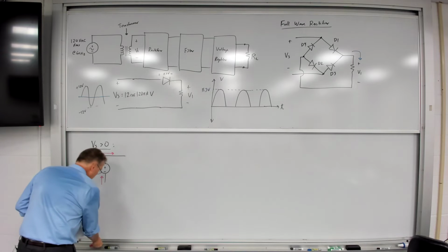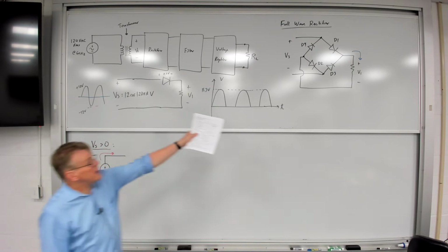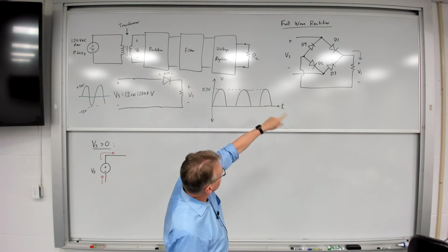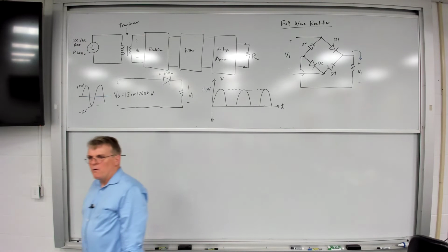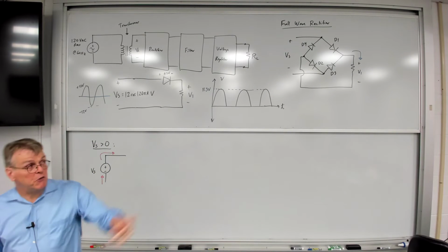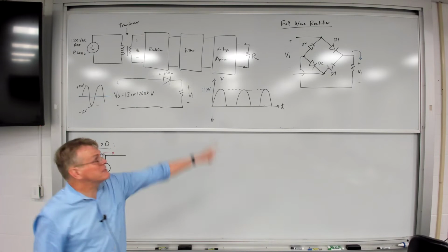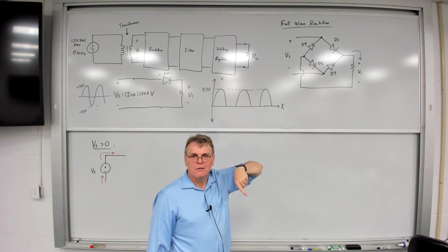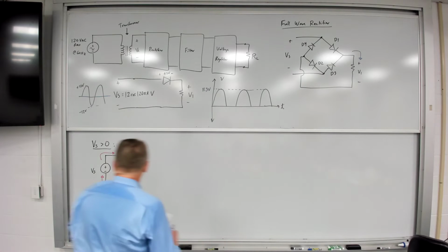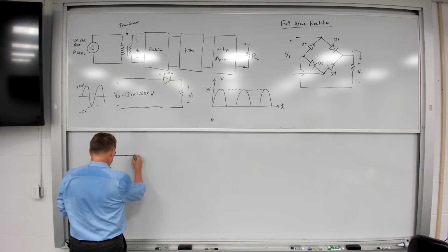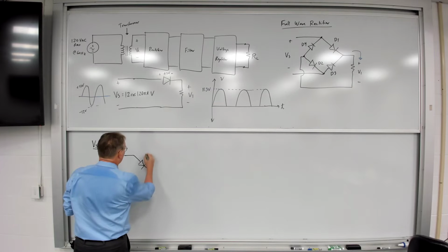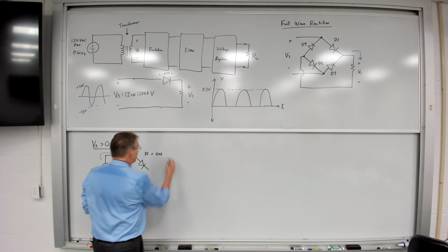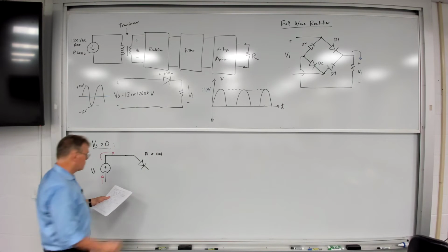So looking at this, let's look at our 2 diodes. So if the current flows into the top, it can go in 2 paths, D1 and D4. Which path can that current take? Can it go through D4? Can't do that because it'd be entering the cathode and coming out the anode. The only possible path is for the current to go through D1. And so in this case, D1 is going to be on. Current's going to flow through D1.